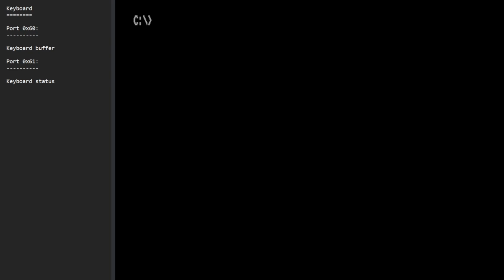But I actually think that this is only necessary if the interrupt request was in service with the CPU. And it's really only required to reset the in-service register, not the interrupt request register. And in our case, the interrupt request is never in service with the CPU because we never let it reach the CPU. We just deal with it ourselves.